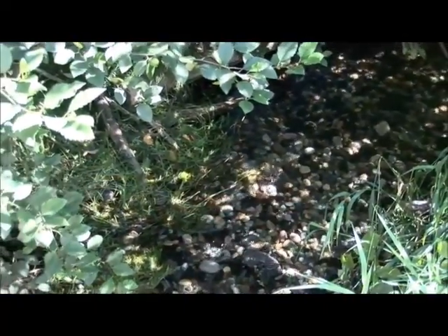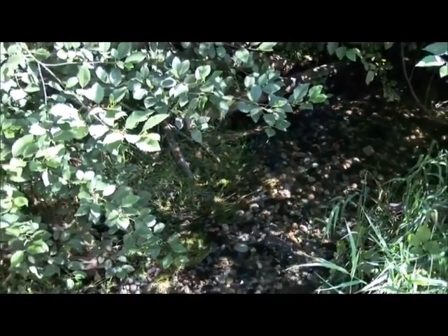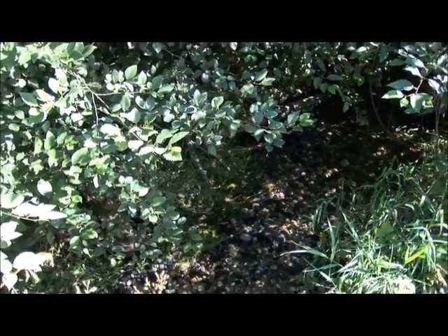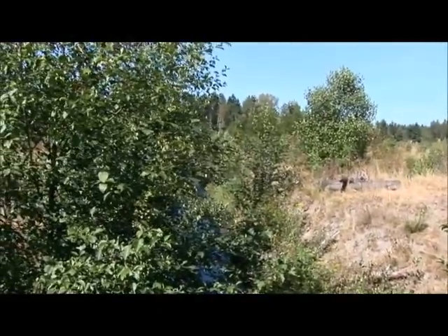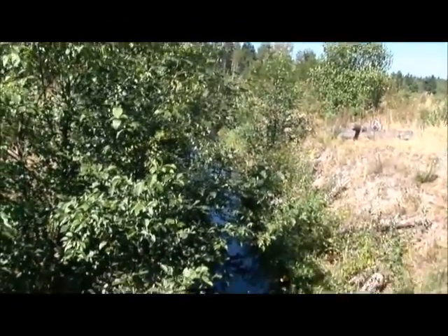and everything off. After the storm scepter, it then goes into stilling basins we've made, so it's more of a little marsh at the outlet, and then a little channel before it hits the main channel. So we've got various levels of treatment, so it's more of a protection because we weren't too sure how the industrial component would be. We don't know what kind of industries are going to be coming in here, and we really want to protect the creek because this creek, as we said, we've restored it and we've got a salmon run in it. So we need as much as we can for water quality.